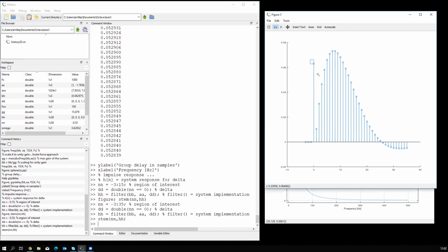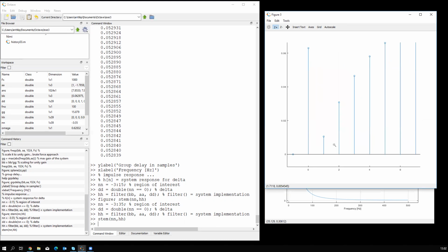This is the impulse response of a second order system. So basically the maximum delay of data on that system is 2. Or actually it's the minimum delay. Minimum delay is 2. If there's anything after the minimum delay, or the highest order delay, if there's anything non-zero here, then it's an IIR system. So definitely an IIR system. Most definitely.